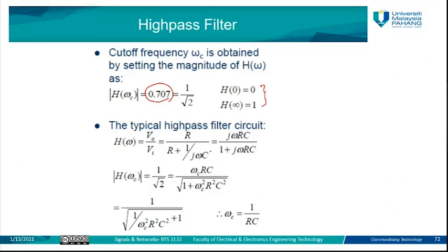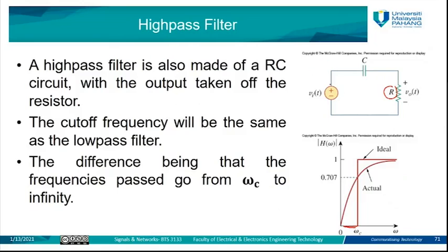So this is the derivative, same as we did before. You need to redraw the circuit in the frequency domain. You need to assume V in. So you can say this one is V in of S minus VC, which is the voltage across here. This plus minus, for example, this is VC plus, I mean minus V out equal to 0.